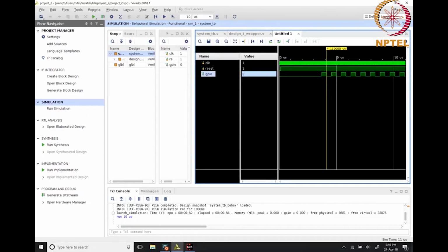And of course, what you can also see is after a certain amount of time, that is 4.55, so in this case, I think 4.55 minus 4.11, yeah, 44 clock cycles, you have the signal going back up again. So that includes the 41 clock cycles for the XGPIO and 3 clock cycles overhead for the while loop. And from there onwards, you should find that it's basically a repetitive pattern. And if you continue simulating, you will find that this goes on endlessly.